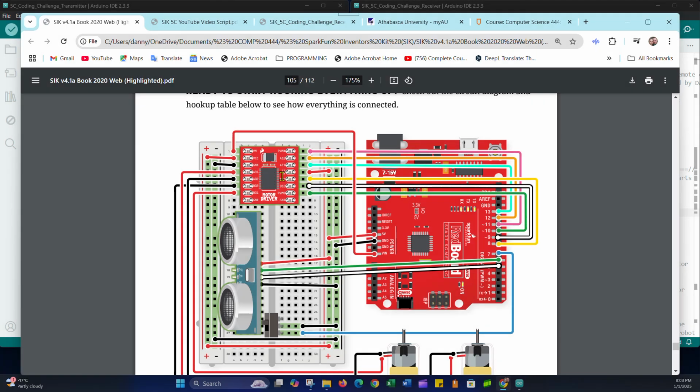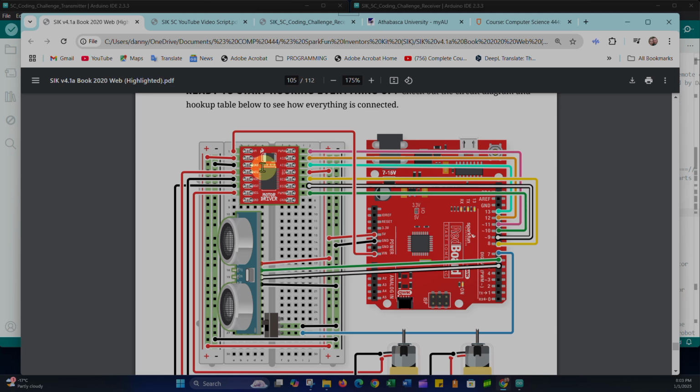There are lots of motor drivers out there though. The motor driver itself gets its power via 5 volts from the microcontroller. You can see the VCC and ground are hooked up to the power rails of the breadboard, which are hooked up to these power rails. They're tethered together, and ultimately are getting their power from the 5 volts and ground of the microcontroller. However, the motors get their power via channel A's output 1 and 2, and motor 2 gets its power from channel B's output 1 and 2, which ultimately go to the 2 motors here. Those are powered via the power that's coming in through the VM pin, VM for the voltage to the motor.